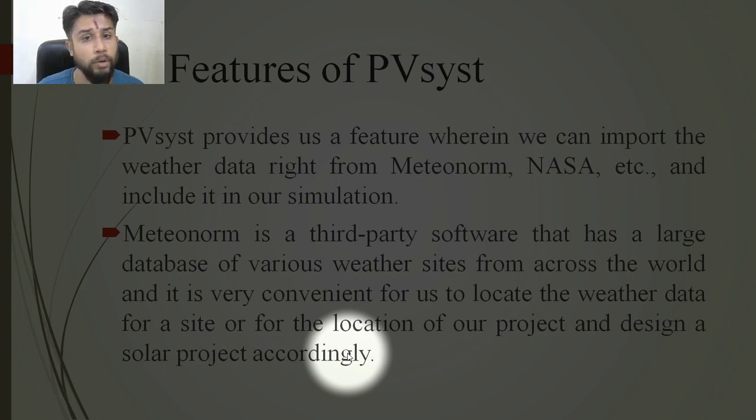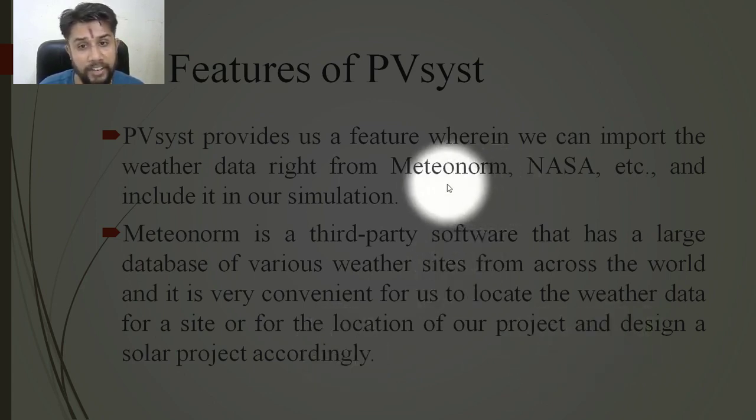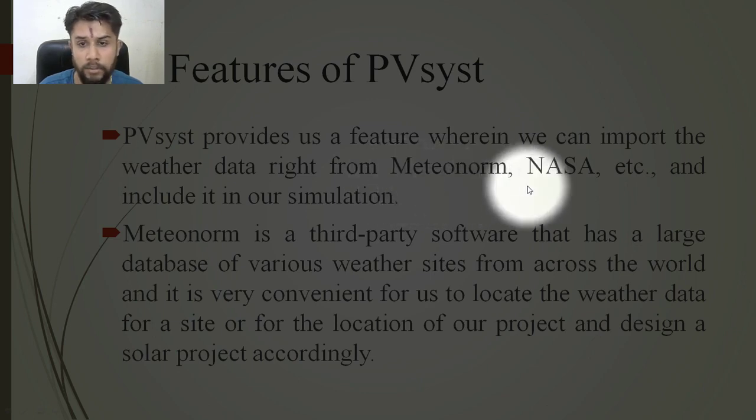PVsyst provides us a feature wherein we can import the weather data right from Meteonorm, NASA. There are other agencies which can provide us the weather data for our application at that location. So this can be easily incorporated in the PVsyst tool. But generally we all prefer this Meteonorm data for the calculation purpose.